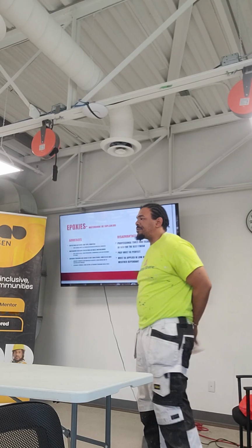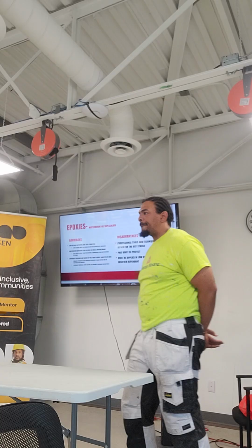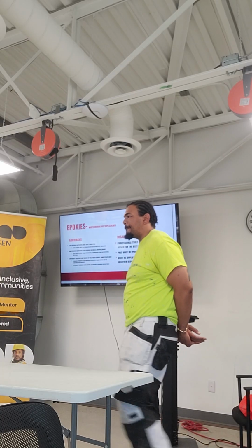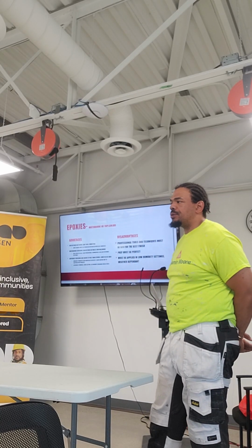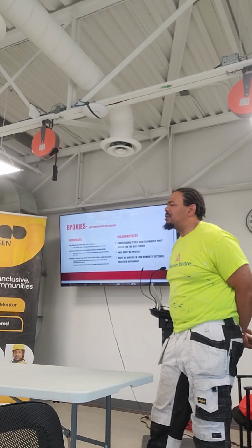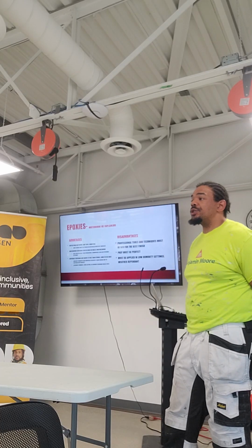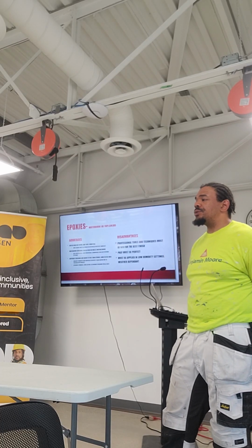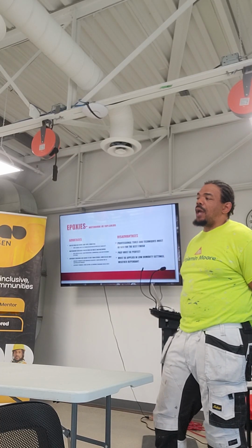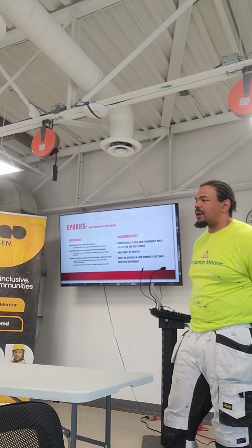So why can't you just use concrete, self-level it, let it dry and then pour the epoxy? You can. A lot of people do. Yeah, because you save money and all that. Not really. Even with self-leveling concrete, you still should use a primer, because you're introducing... Yeah, so you still roll the primer. There are epoxy primers that you pour out.